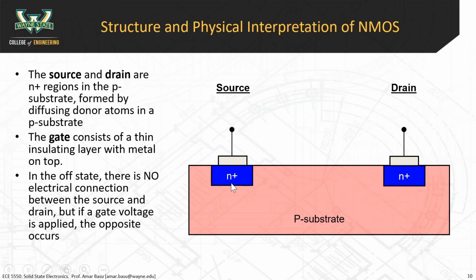If you remember from last chapter, these are tunneling type contacts. So you have a metal semiconductor junction right here. All right, a metal semiconductor junction can behave as a diode, or it can behave as an ohmic contact. If you have a really highly doped semiconductor next to the metal, then it forms what's called a tunneling type contact, and it's always ohmic, or very ohmic-like. So this forms an ohmic contact here.